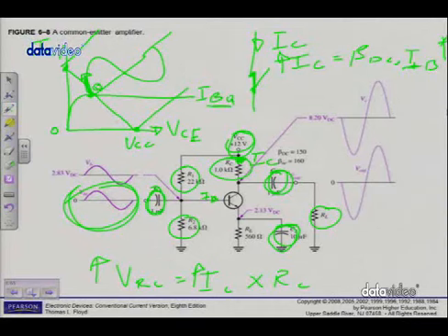And that's what I always tell the students every time I discuss electronics. As long as you know Ohm's law and Kirchhoff's laws, no problem with electronics. So, what does Kirchhoff's law state? Kirchhoff's voltage law specifically. If I simplify the circuit, let's take that 12 volts and I put the battery here so that it looks more simple.